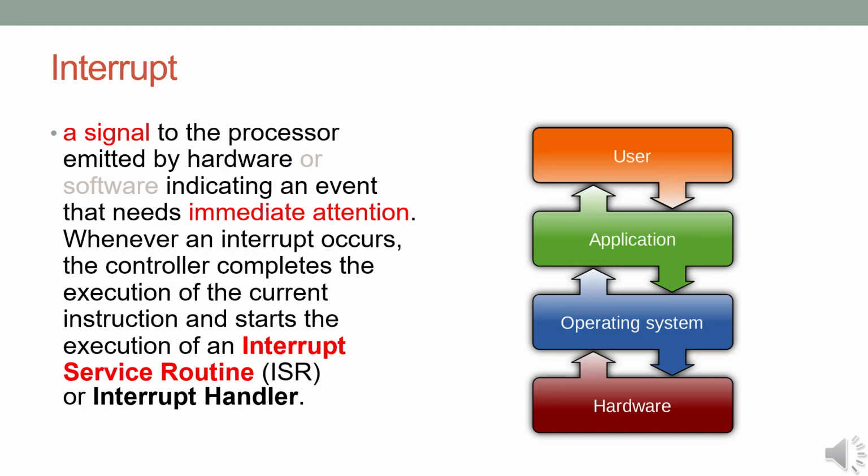This model is especially powerful on platforms like the Raspberry Pi, where applications don't interact directly with hardware. Instead, they communicate through Python packages like RPi.GPIO or gpiozero that run on the operating system. These packages manage the hardware layer and abstract the complexity of handling low-level hardware interrupts. This allows developers to use simple, high-level code while still leveraging advanced features like ISR and event-driven control.